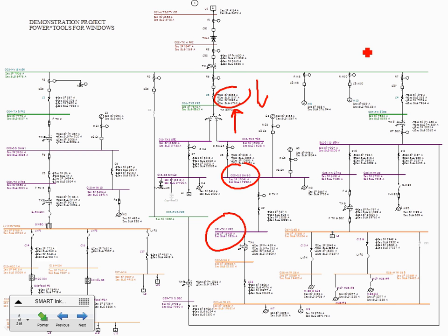So that's the major reason why we use a one-line diagram. It gives us short circuit, and out of this calculation, you can get a label that looks like this one here that says warning, arc flash hazard. That's a big deal, because every panel has to have a label like this. So anyway, without stealing your thunder here. No, that's kind of what I was looking for. Yeah, but this is exactly what you're going to be mostly using a one-line diagram for: short circuit analysis and coordination and so forth.